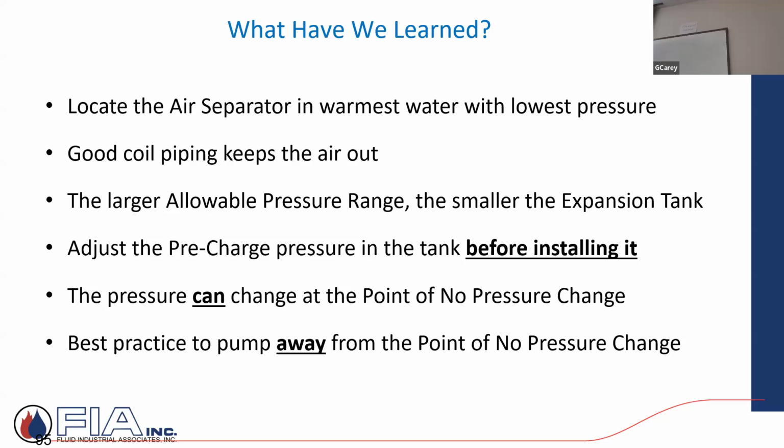Where is it going to be located? What's the weight of that water? If there's all this pressure, can I increase the relief valve setting? So now I have more of a range of flexibility, I can use smaller tanks. Technical, but pre-charge before installing. Now that's not what you guys do, that's what the mechanical contractor is going to do. But if we write it somewhere, say, pre-charge it to this and do it before you install it, you give them a pretty good chance.